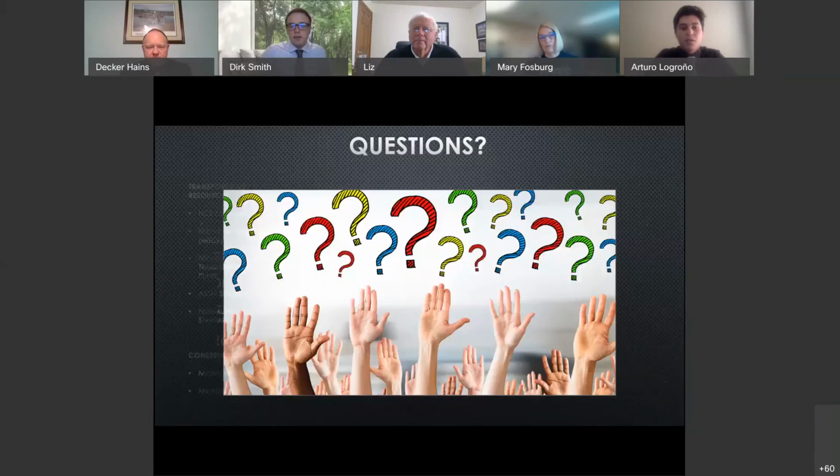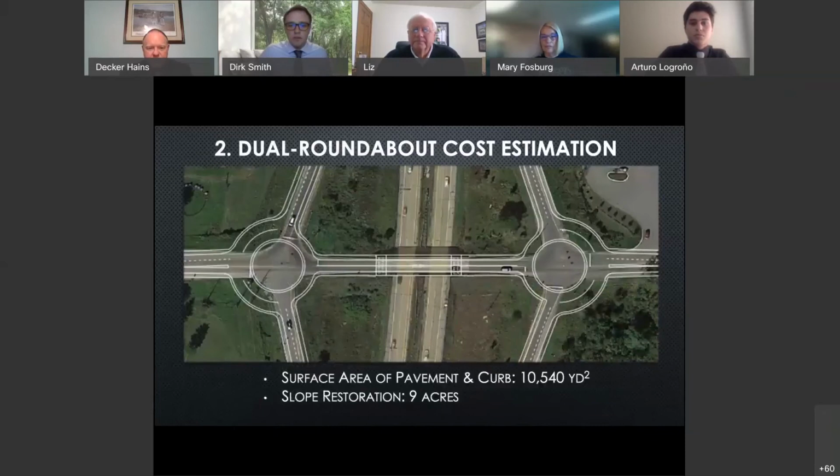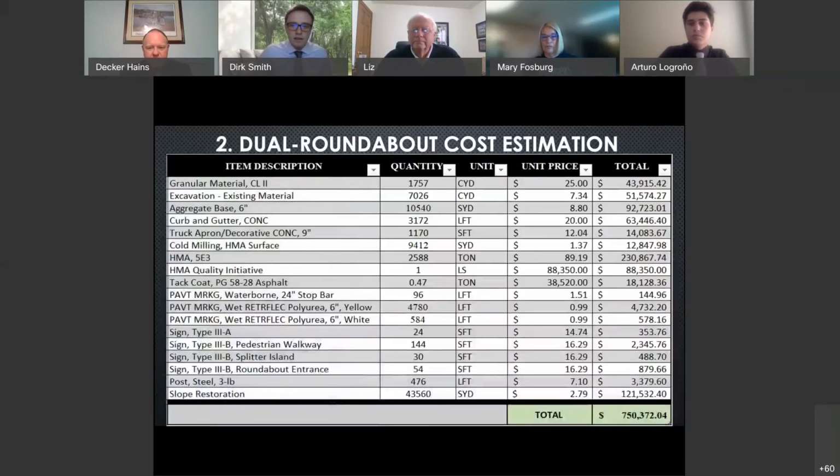To expand on that a little further, we took on the roundabout design to ensure we had an accurate bridge width when we designed our bridge. So we focused more on the schematic sky view design, what it would look like for lane widths. So we really didn't get into detail of HMA layers or thicknesses. We went with typical from what we've experienced in talking with our sponsor MDOT for a cross section of what is expected on a roundabout, like if it's 3 layers, stuff like that. It's taken care of in our estimate.